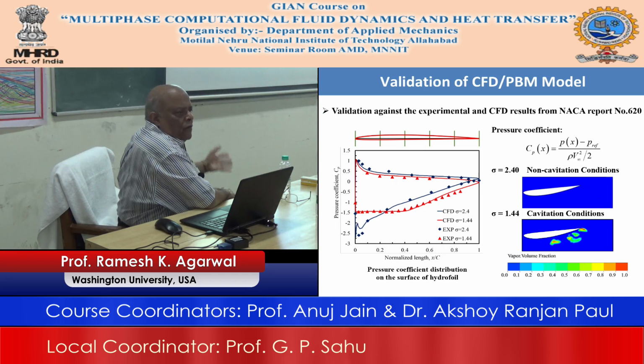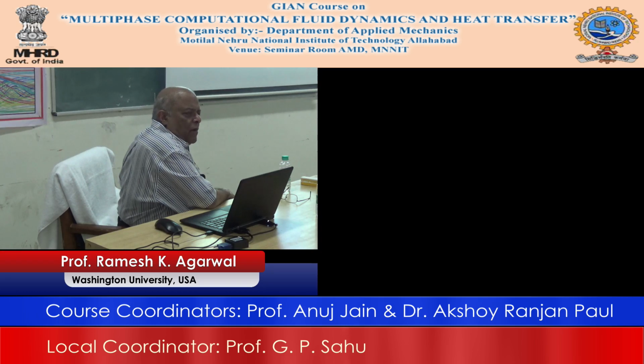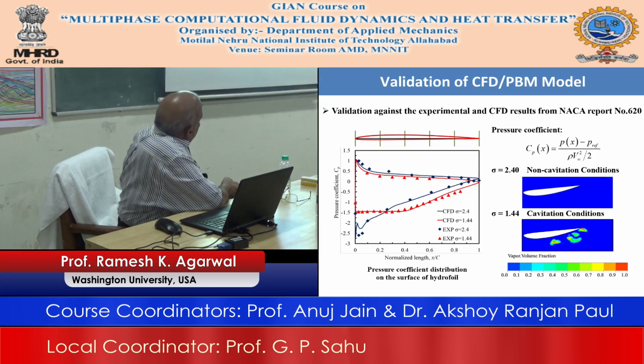For this particular case, the cavitation number is very different than what we had for the case of the previous pump, where we had 0.19 and 0.20. You see that this is no cavitation and this is a cavitation, and the cavitation has started. These are basically lumps of bubbles showing the cavitation.